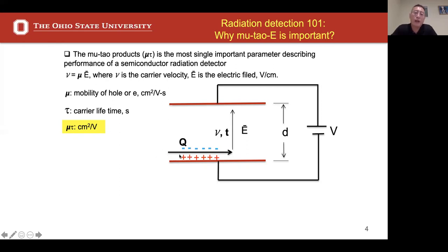So I have radiation coming from the side and producing charged electron-hole pairs, or electron-ion pairs, which then travel, driven by the external voltage and electrical field, from the anode to the cathode. So look at this definition. The carrier velocity is proportional to the electrical field you are applying, right?